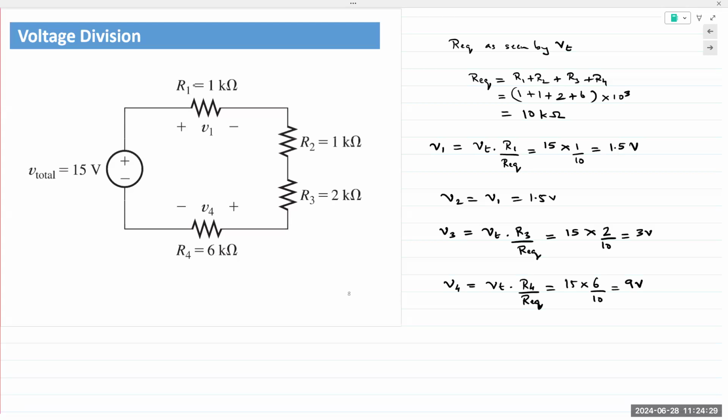Yes, that is correct. The question being asked is why can we use voltage division? And the answer is that they are in series. Current, of course, remains exactly the same for series connections. There's no other pathway for the current to go, right? So in a series connection, the current is a result of all the resistors working at the same time, the cumulative effect. And so it remains the same value for everything.